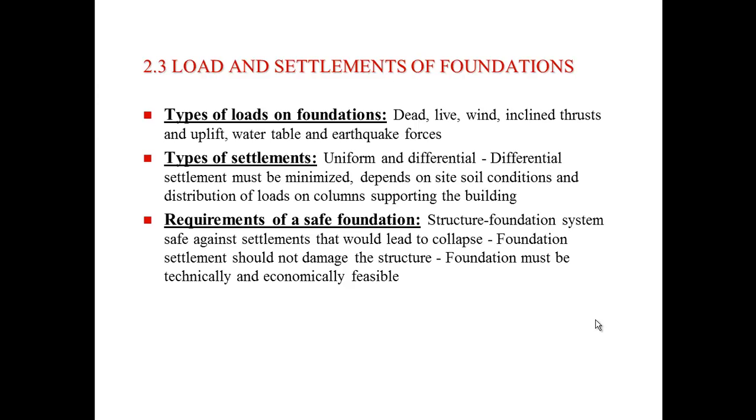Requirements of a safe foundation. The structure foundation system must be safe against settlements that would lead to collapse. Foundation settlement should not damage the structure, and the foundation must be technically and economically feasible. We don't want to spend all our money on the foundation, but by the same token, that's what's going to support our entire building, so we have to look at it from both standpoints.